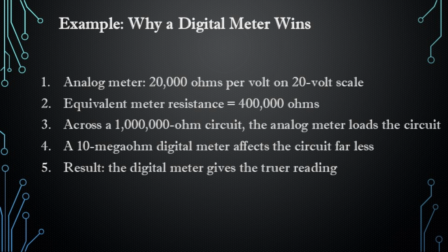Once you start dealing with control modules, sensor circuits, reference voltages, and other low current electronics, a meter that disturbs the circuit can easily send a technician the wrong way. So this was not just a convenience shift from analog to digital. It was a real improvement in diagnostic quality, and in a lot of ways, that is the lesson.